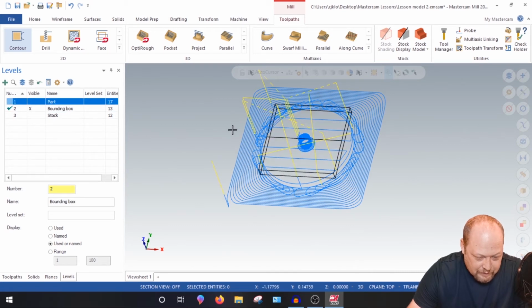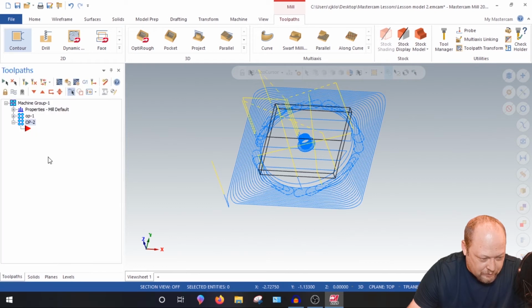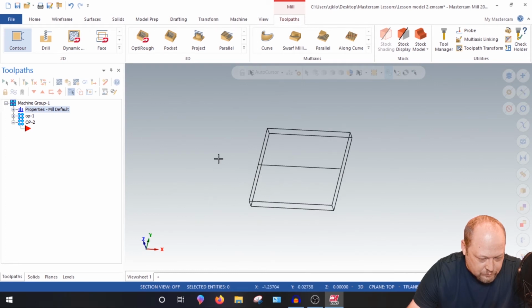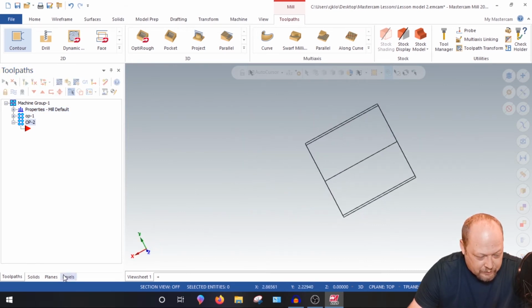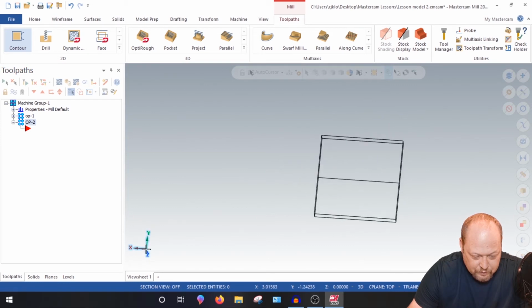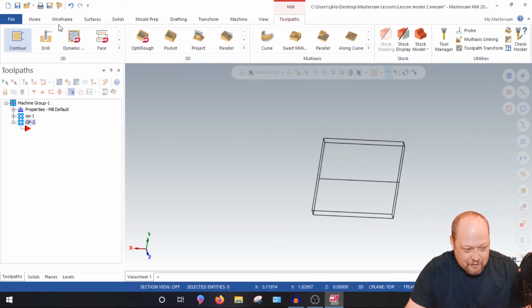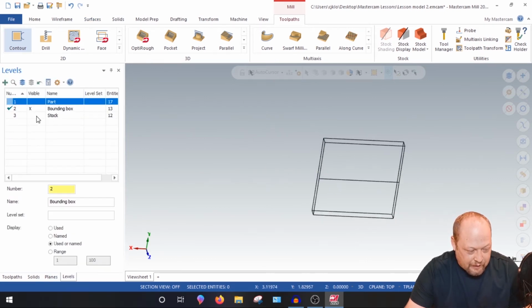Okay. Now what you're going to want to do, go back to your toolpath, select group to turn your, or sorry, this right here to turn your toolpaths off. And you need this selected. So this has to be selected in that, and that'll turn your toolpaths off. So now from here, what we're going to do is, so op1, op2, we need to make a second op. We're going to flip the washer over. Okay, then the two corners of the stock, no, the center line of the hole is going to be the XY0.